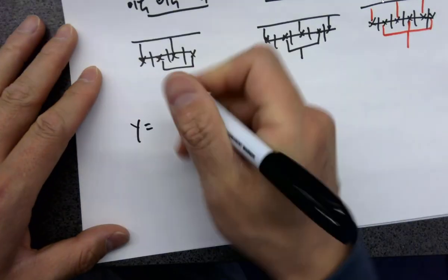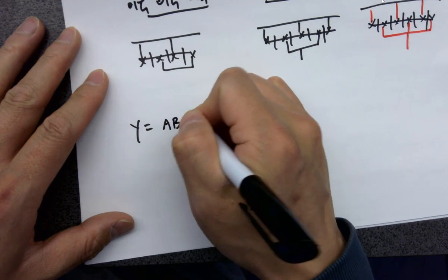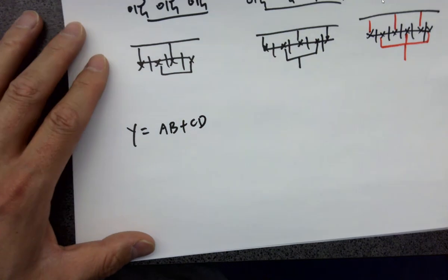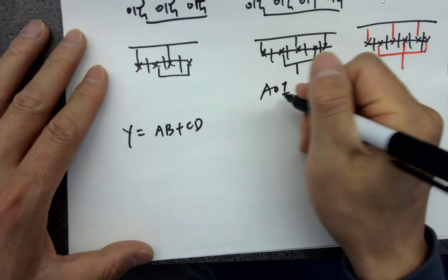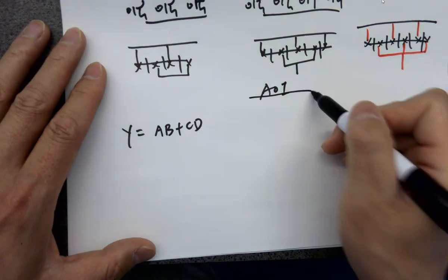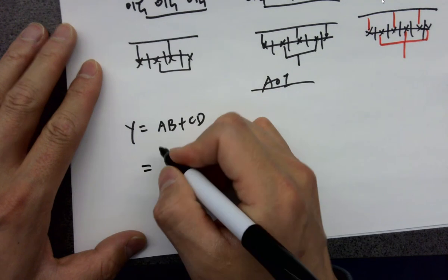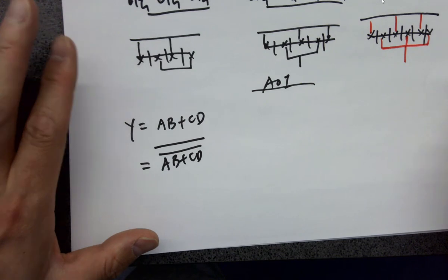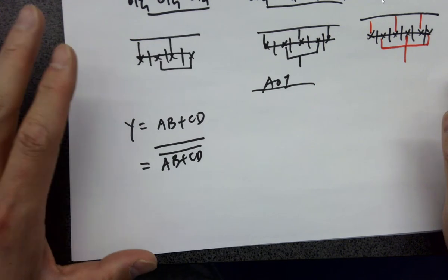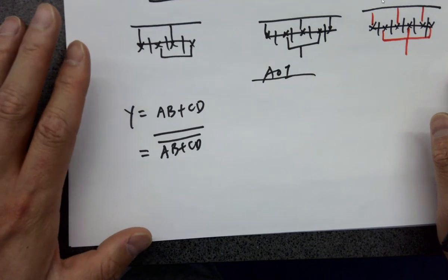And also De Morgan's law, you have y equals ab plus cd, right? And because of the AOI logic, it's AND-OR-inverse. So eventually it's getting inverted. And that is why we need the two bars on the top. So eventually just leave one bar, and then we can draw a schematic from that logic equation with a bar on the top, right?